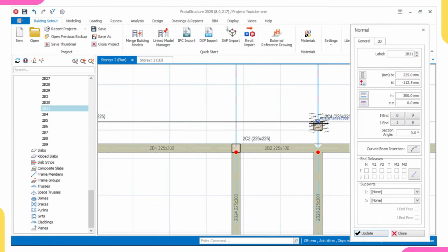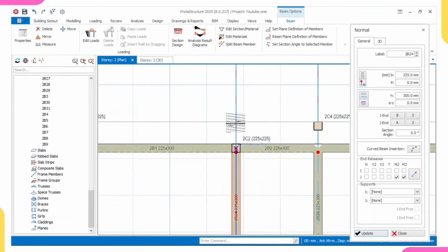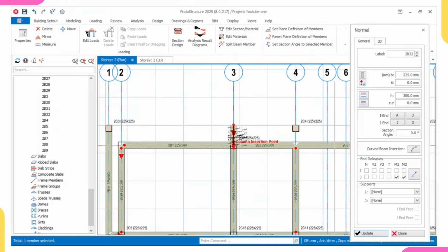from here to, sorry, I should have introduced this column, because this column will be serving as a cantilever. So I should have introduced a beam here, pull it out, because this beam will be acting as a cantilever. It will carry this beam that will run through here.